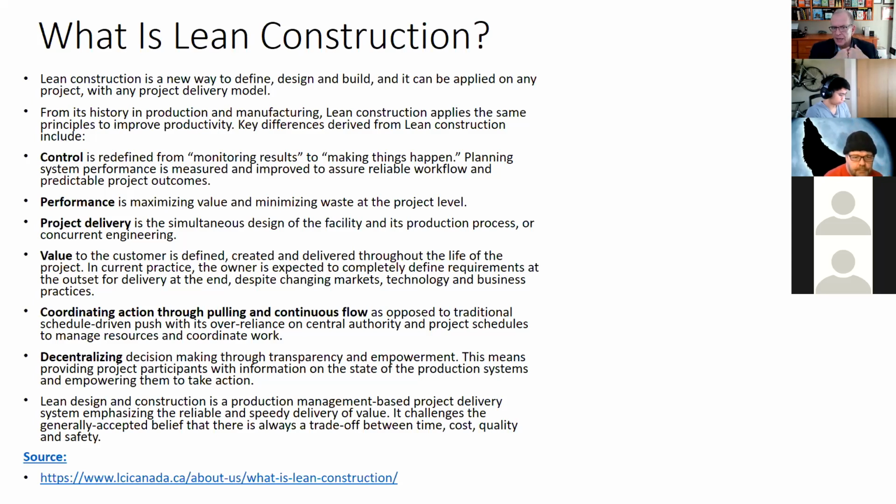So if there's something that can be influenced in the design by the people that actually do the work, major subcontractors, the GC, etc., then that is where Lean really excels, right? We can do Lean on a lump sum, but we can't do the full-out Lean. We can do Lean with the Last Planner System and the scheduling aspects, the different layers of scheduling involved, but we can't influence the design to add the most value to the client. So that's where that sort of interrupts.